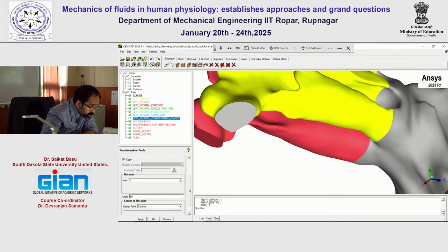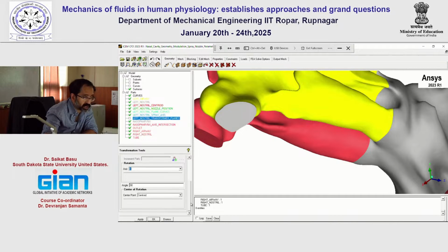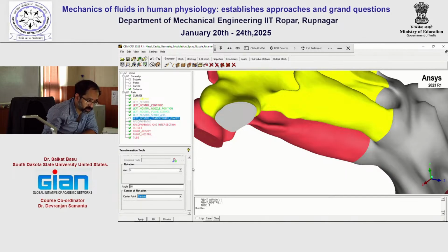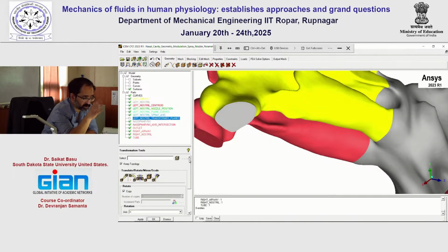Now you can pick any axis to begin with. So let's pick the x-axis. 90 degrees is fine, but make sure that the plane you are about to rotate is going to be rotated about its centroid. You can rotate it about the origin of the overall space or about any other point. But since I'm trying to figure out the centroid, the idea is to rotate it about the centroid, because eventually the intersection point of those transformed planes would give you the centroid.